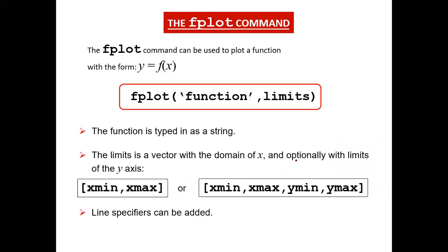Then another one is how we can create a plot for a function. Whatever equation we have, the function of x, here the equation is y equal to f of x. If we have this type of function, how can we generate it for the plot? We can add it for fplot. Then what is the function? What is the limit value? The limit value we can also give when we are going to generate the function plot.